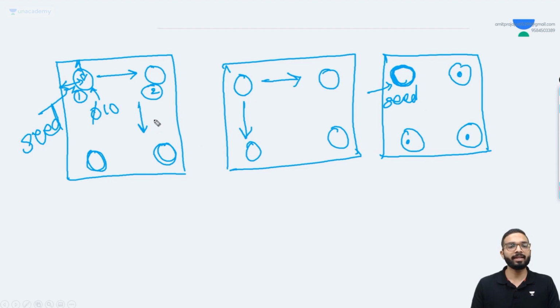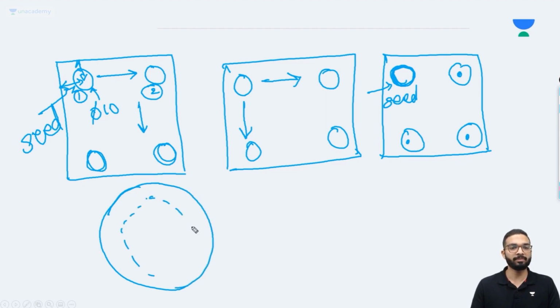The next type of pattern that we have is a circular pattern. Let's say I have a disc here and I want 5 holes on this PCD like this. What I will do is that I will simply create the first hole, define it by giving it the dimensions, diameter and everything. Next what I will do is that I will go to simply a circular pattern and enter the number of instances as 5 and give it the spacing. You can either select equal spacing or you can give the angle that you desire. If you select equal spacing, it will create five equally spaced holes like this.